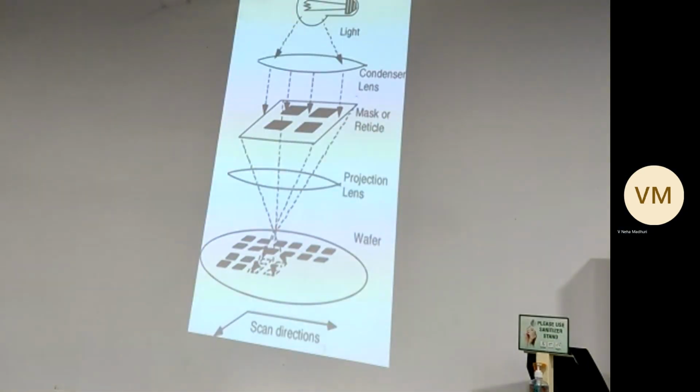Depth of time. Again, time. So you put it for 1 minute, this much etching. So 4 minutes, then that much etching. So that's where the process engineers, right, help us. But we have to become our own fabricator. When we are fabricator, we have to study some chemistry, some physics to understand what is the reaction happening. They're all chemical reactions, right? When the acid meets the photoresist, it will dissolve this, and the byproducts are this. That kind of process is happening.